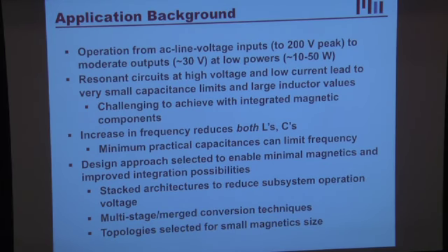If I turn up the frequency, suppose I want to just dial frequency in my circuit, what that turns into, instead of large inductors and small capacitors, I get medium-sized inductors and ridiculously small capacitors. And the problem is I very quickly, as I turn up frequency, scale out of the range where I can realize that because my intrinsic device capacitances that I need to carry the current are too large for the system. So that's a different constraint besides just loss, it's just component value scaling that prevents me from going up in frequency as I'd like in order to miniaturize my system.